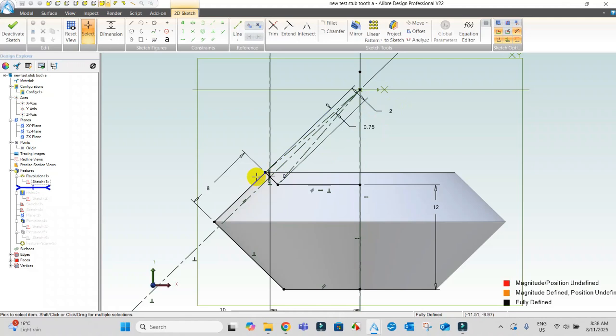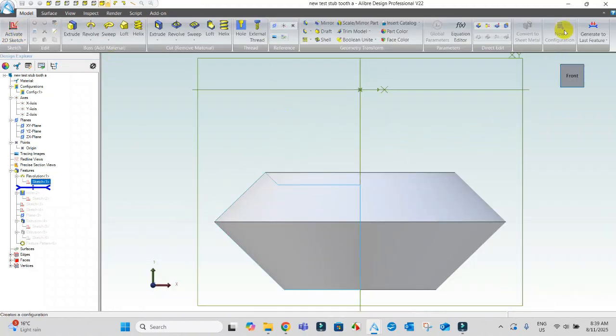It makes the teeth a little bit more vertical. It's the same cutter though, but it also gives me the ability to make the face of the teeth a little bit more vertical rather than the 20-degree pressure angle. It will alter that to some degree. And also, I can make the cutter go longer. 6.5 was about my limit, now I've got that out to 8 millimeters. I'll deactivate the sketch and we'll have a look at how this works out in real life on the teeth.